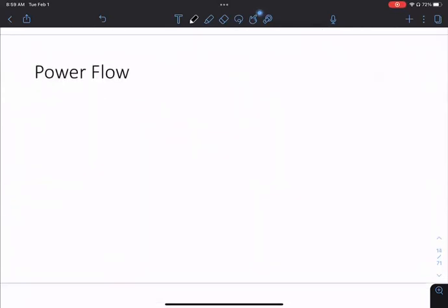So again, we'll start with some input power. Okay. So think of this P in as the power coming into the rotor from both the mechanical power from the gearbox and injected power coming from the grid. Think of this as the total power that's coming to my rotor. And we want to compute how this thing gets divided up.